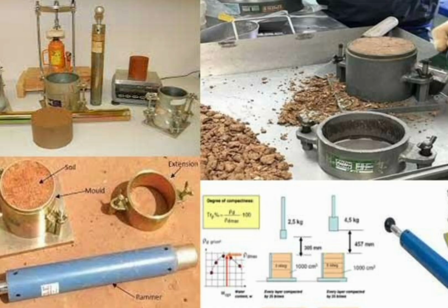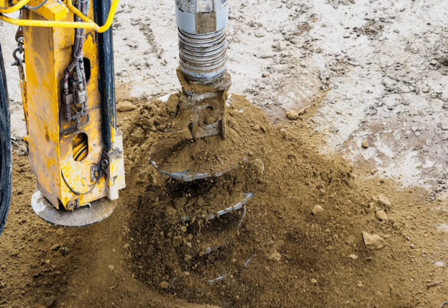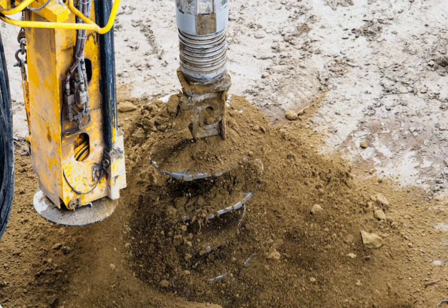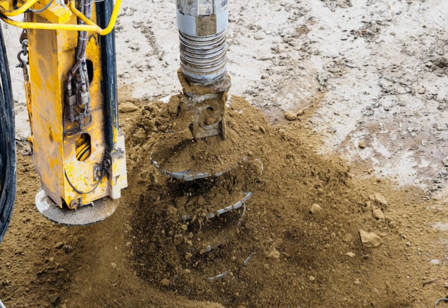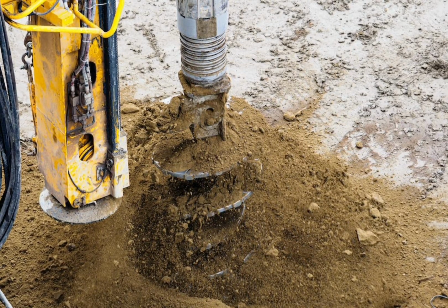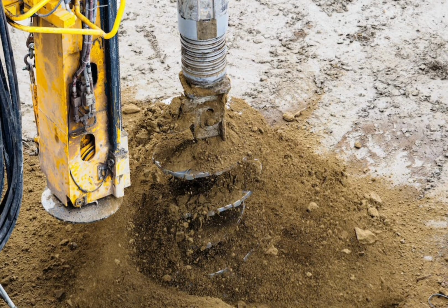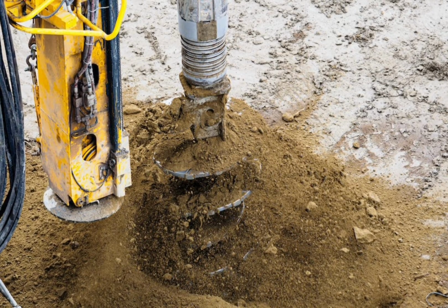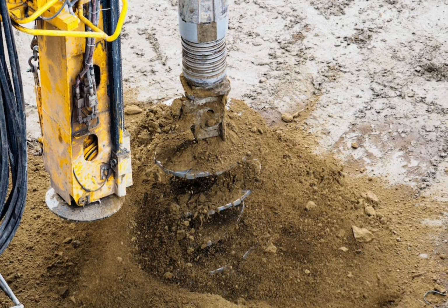This test is the cornerstone of all earthwork projects, from highway embankments to building pads. The next set of tests are the heavy hitters of geotechnical engineering, the strength tests. The direct shear test is a relatively simple way to determine the shear strength parameters of a soil, its cohesion, C, and its angle of internal friction, phi.